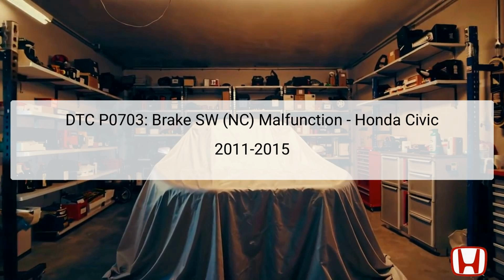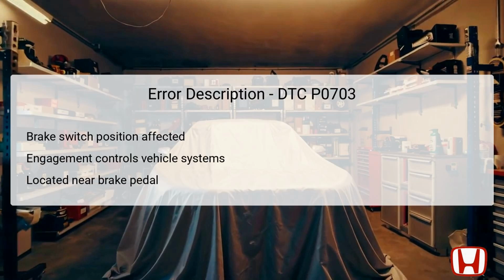In some situations, simply pressing the brake pedal for an extended period may inadvertently lead to this code being stored in the vehicle's computer system, highlighting the importance of thorough diagnostics before making repairs. The error indicated by DTC P0703 directly impacts the brake switch position, which plays a crucial role in the vehicle's operation of several systems. This brake switch generally informs the Honda Civic about whether the brakes are applied, which affects functions such as cruise control and the idle stop feature.